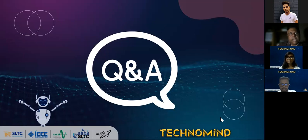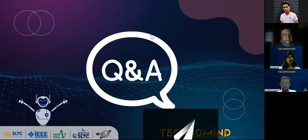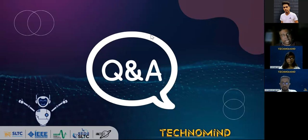As I mentioned earlier, you don't have to write your algorithms from scratch. To learn how it happens, you can use one of the existing algorithms first and put it on the robot and see whether you can use it. Normally, once you have implemented your SLAM algorithm in software, first you move the robot in the environment, say randomly. By doing that, the robot can collect environmental features and build the map. After that, if you ask the robot to move from one place to another, it can move. It is a good alternative to building an a priori map.